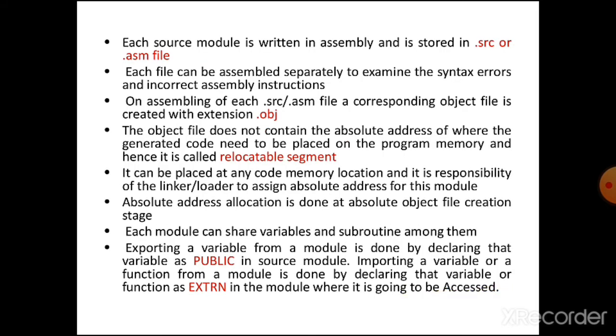Exporting a variable from a module is done by declaring the variable as public in the source module. Importing a variable or a function from a module is done by declaring that variable or function as extern in the module where it is going to be accessed.